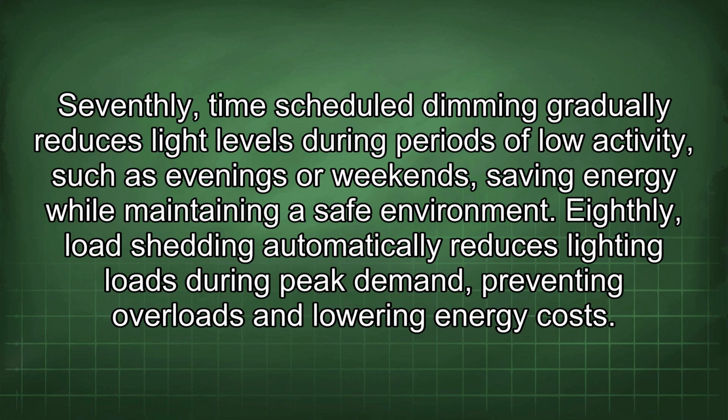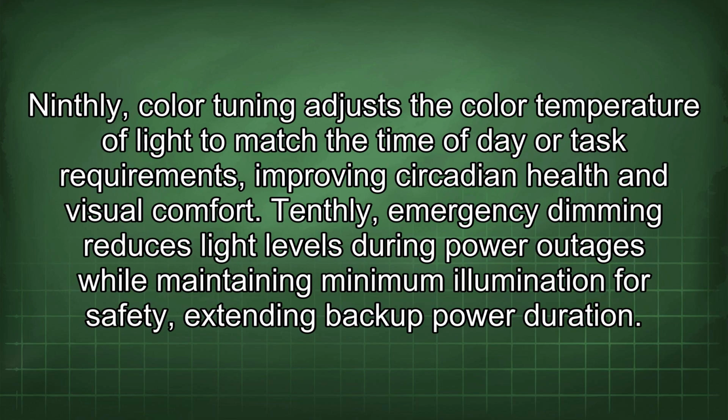Eighthly, load shedding automatically reduces lighting loads during peak demand, preventing overloads and lowering energy costs. Ninthly, color tuning adjusts the color temperature of light to match the time of day or task requirements, improving circadian health and visual comfort. Tenthly, emergency dimming reduces light levels during power outages while maintaining minimum illumination for safety, extending